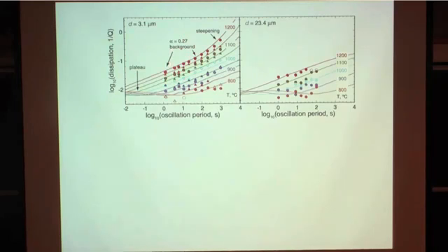That's the high temperature background. And you can see by varying the temperature, we have a fixed range of oscillation periods. By varying the temperature, we're really shifting this background, the absorption band, around quite a bit. Right? And again, we see a grain size dependence of this lower dissipation at coarser grain sizes.